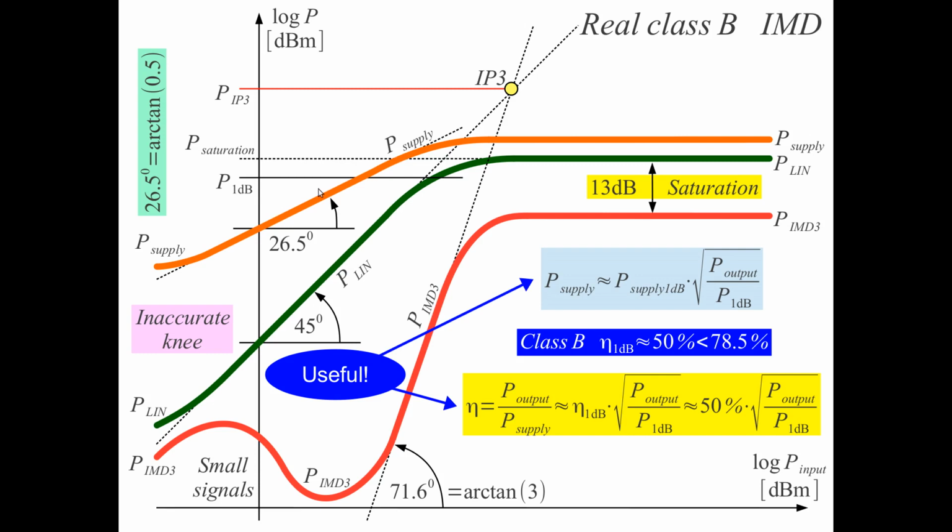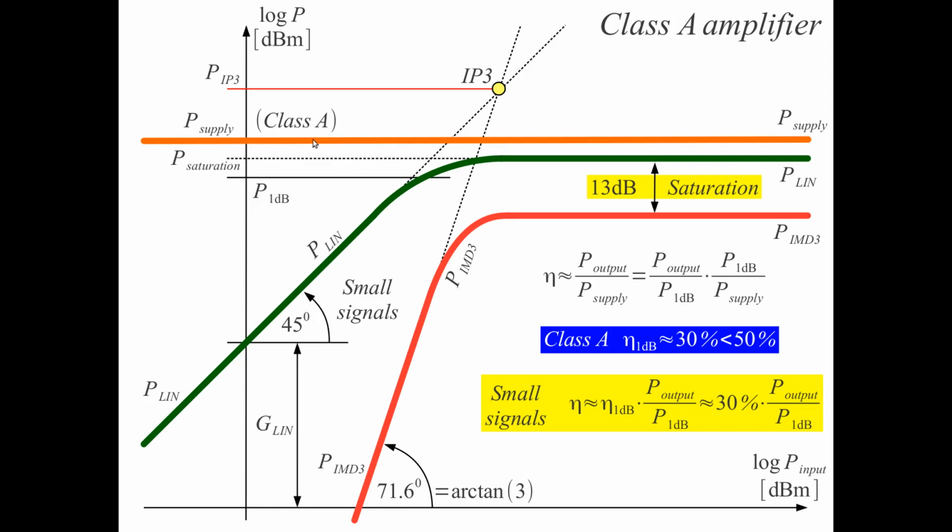The current increases linearly proportional to the input amplitude, while the output power increases with the square. We do not have the power consumption anywhere on this drawing. But still, the difference between the two, in the interesting region of operation at small signals, stays much smaller than the difference in the class A amplifier.